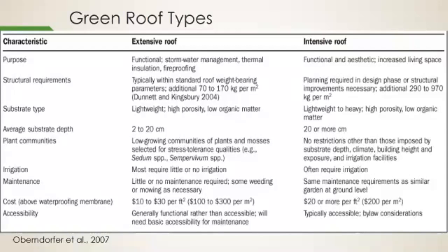So intensive roofs, on the other hand, can go anywhere from, at the lower end, maybe a semi-intensive green roof would be 500 pounds per square foot, up to, once you get up to something like Millennium Park that we'll look at, you can just put as much on there as you want. But generally 2,000 pounds, 1 ton per square foot is about, you could just put about anything on that.